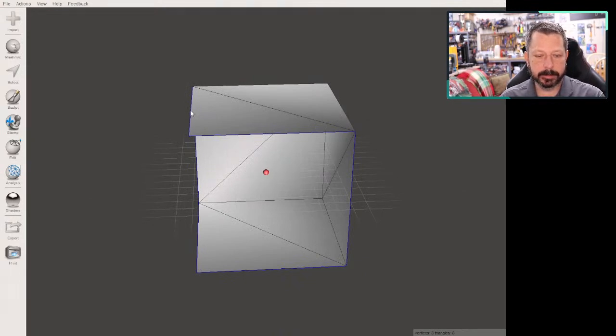You can have other non-manifold types too, where maybe you have 2 faces that share an edge and nothing else. So that could be a problem. Well, 3 faces. 2 faces can share an edge. I meant a 3rd face that can share an edge. You can't really have that because it makes kind of like this infinitely small connection between the parts, and it probably won't print.